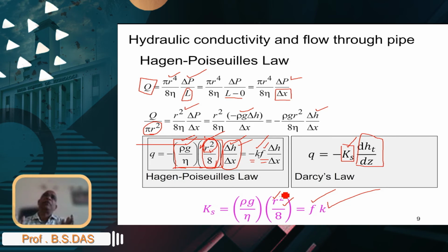So if you think about a radius of a pore which is of a maximum size, so maybe an R max, you're talking about all pores smaller than and inclusive of this R max as water containing pores. That's when soil is fully saturated. And so when you talk about a saturated hydraulic conductivity, you talk about this R to be the maximum possible size of the pore which is present in the soil, which is also saturated, right?